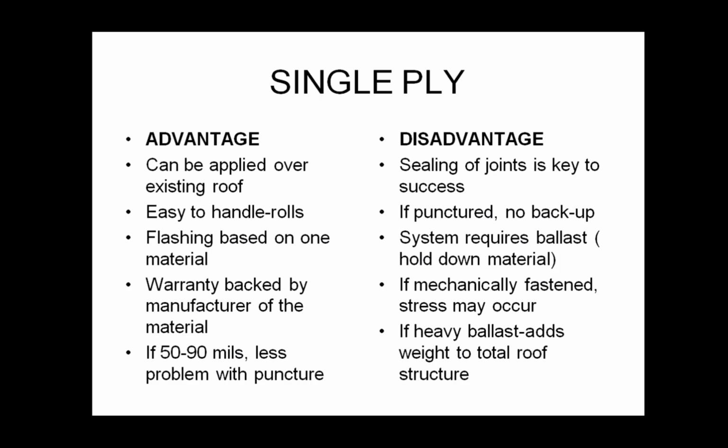And lastly, if you need heavy ballast to hold in place as a hold-down material, you're adding total weight. You could be adding total weight to your roof, as opposed to some of the other roofing materials, which may be more complex, thicker, more complicated, but actually be lighter.